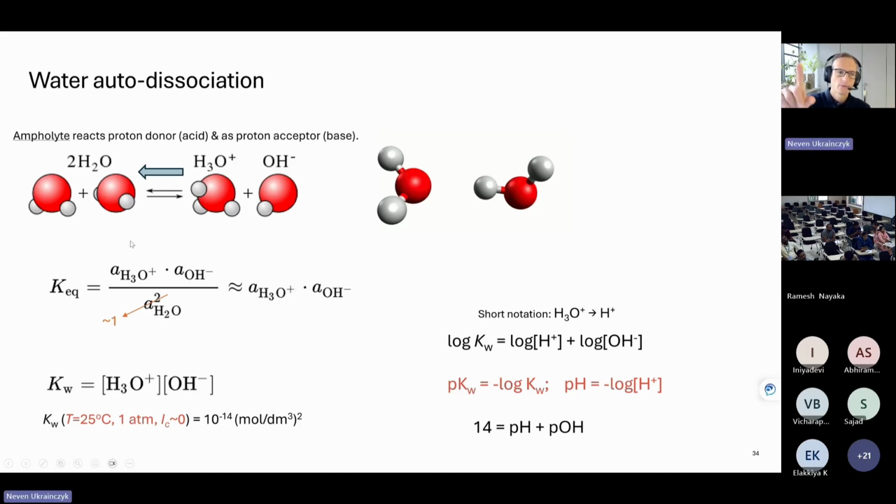So this is what we had before, if you know the solubility of portlandite, and we have put the common ion, which is the OH minus, with calcium hydroxide. So we put it inside, and because this constant should stay the same, it can only stay the same if you move the OH minus by precipitating more Portlandite in that case.